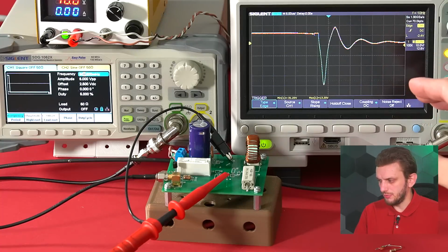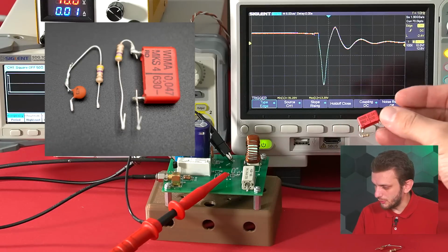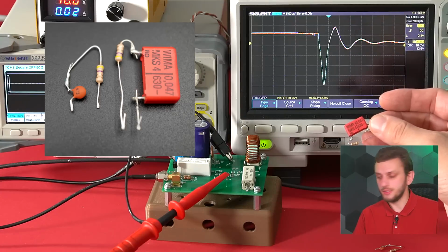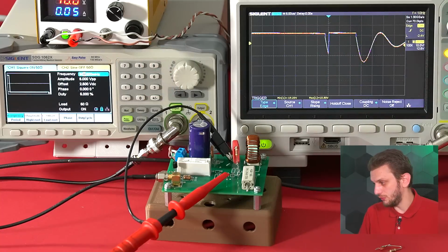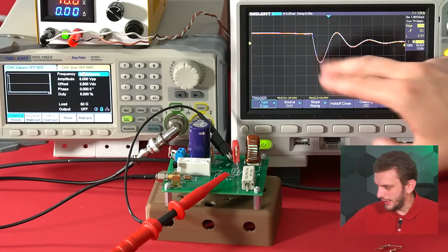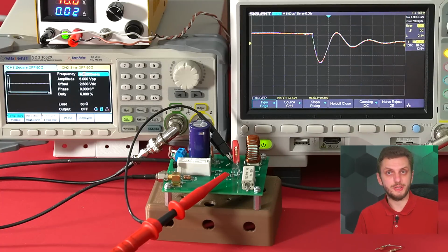So just to make sure if the problem is with the capacitor or with the simulation, I have this other RC network where I have the same 4.7 ohm resistor, but this time the 47 nanofarad capacitor is of film type. So this will definitely maintain its value. If we try this component, we can see the ringing again, and we can see our minimum voltage at minus 19.6. So when the capacitor in your RC network ends up seeing large voltage variations, it's important to make sure that the capacitor actually keeps its value during the voltage pulse if you want the predictable behavior to occur.